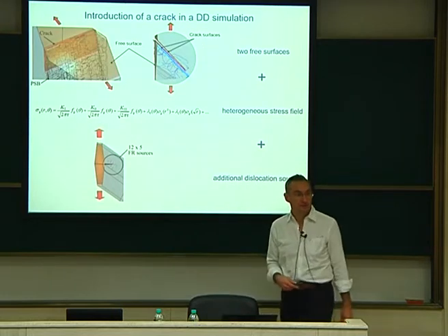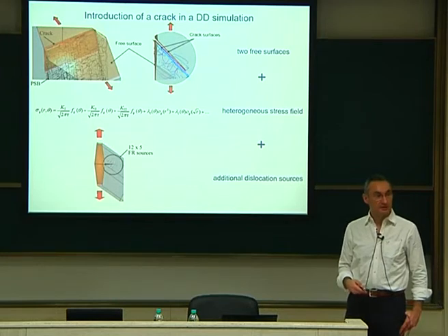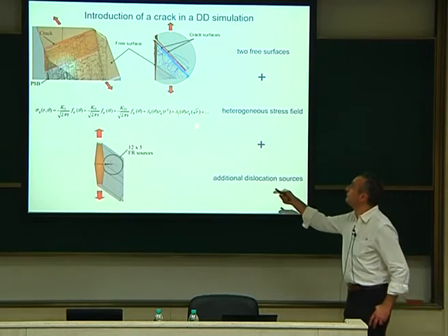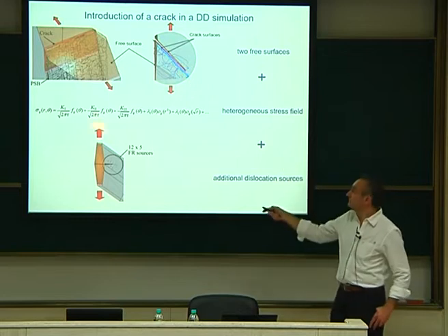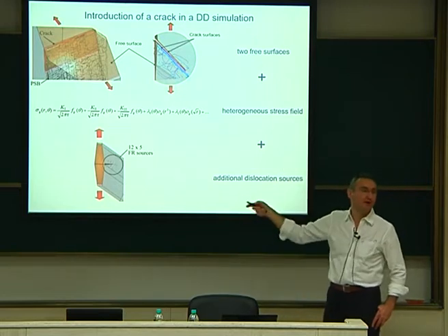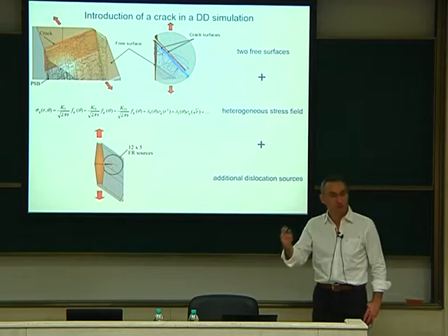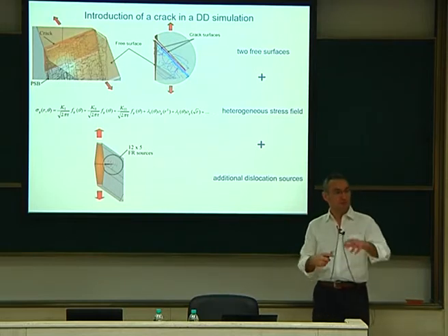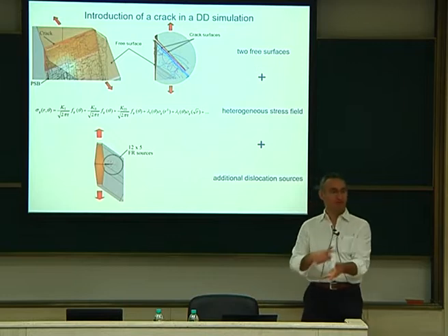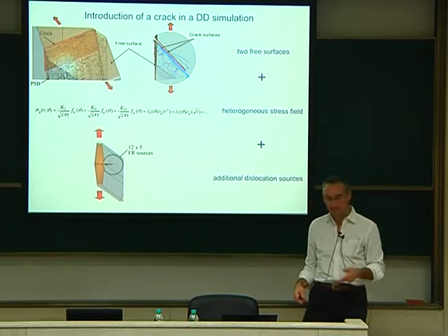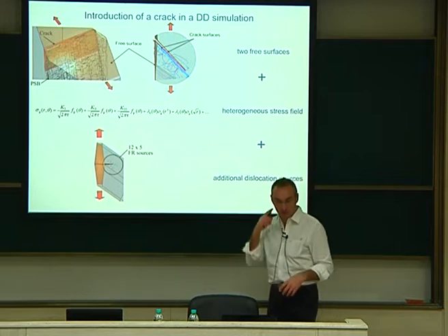And all the r's are being evaluated from the crack tip. Yes. So you compute at each point. For example, if I want to compute the stress at this dislocation here, I will call this formula, which is just a formula. And this just gets added to the global one. Exactly. To the global and internal, yes. So for the dislocation, you have the dislocation stress, the applied one, and the crack. So now you have three fields that you sum up, okay? Just because we deal with linear elasticity, we can sum up. You can superimpose the fields.